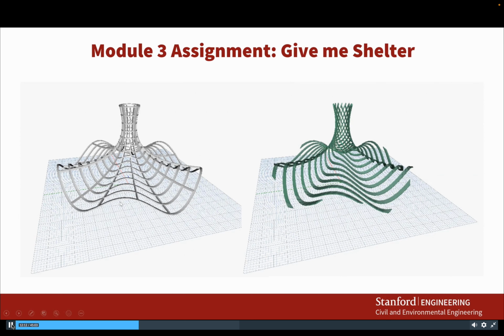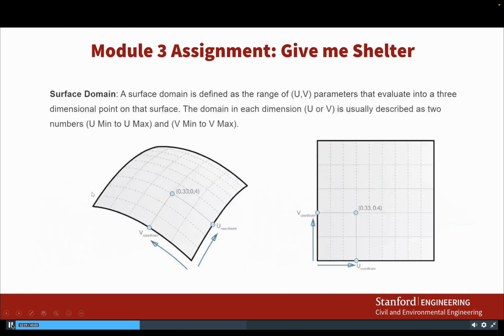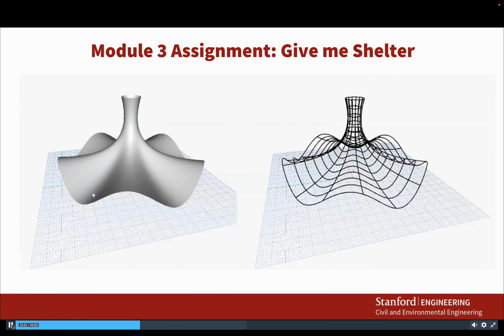One thing is, don't feel forced to do the sweeps in Dynamo. You can actually get the curves. So once you have these curves, you can use adaptive components in Revit to place your geometry. The adaptive components that we've seen so far are point-based, so you would have to change your approach a little bit. For example, let me see if I can annotate here.